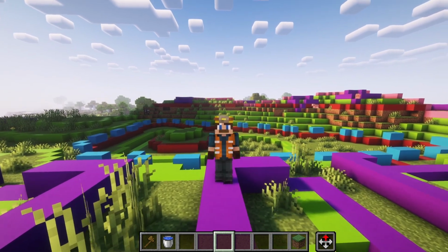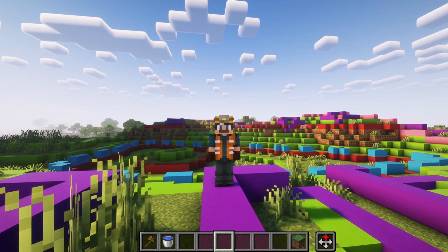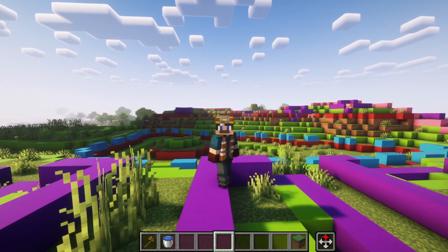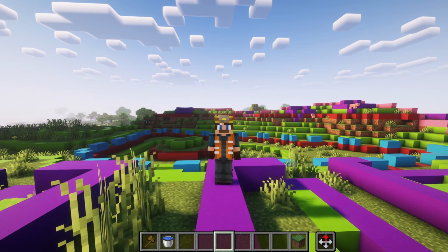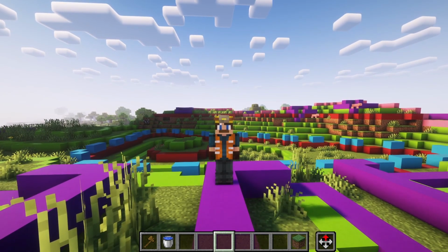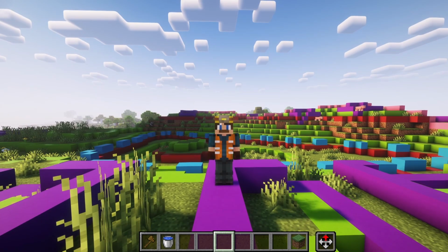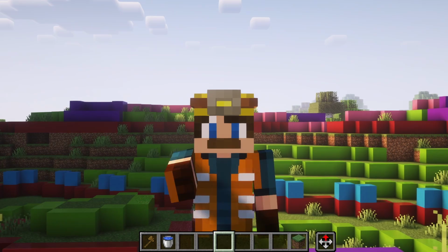Now, a detention pond, as I said before, is pretty similar to a retention pond. However, they are designed to temporarily hold water during and after storm events and then release it at a controlled rate. So normally the detention pond is typically dry during all times of the year except for during or immediately after a rain event. It fills up during the storms and slowly releases water through a structure outlet, similar to the retention pond. Another use for this would be in urban areas or places where immediate drainage control is needed without permanent standing water.